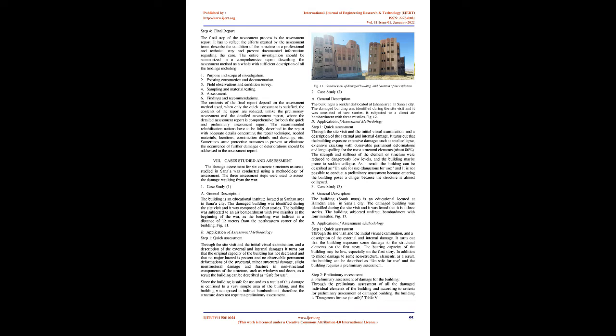The contents of the final report depend on the assessment method used. When only the quick assessment is satisfied, the contents of the report are reduced, unlike the preliminary assessment and the detailed assessment report, where the detailed assessment report is comprehensive for both the quick and preliminary assessment reports. The recommended rehabilitation actions have to be fully described in the report with adequate details concerning the repair technique, needed materials, locations, construction details, and drawings, etc. Sometimes some protective measures to prevent or eliminate the occurrence of further damages or deterioration should be addressed in the assessment report.